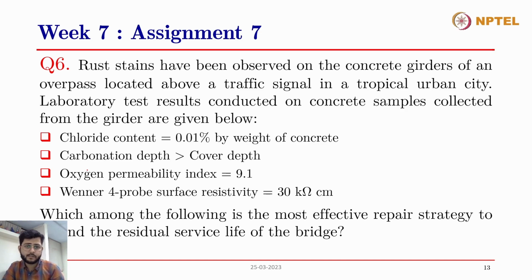The chloride content is 0.01% by weight of the concrete. Carbonation depth is greater than cover depth. Oxygen permeability index is 9.1. The four-probe surface resistivity result gives us 30 kilo ohm centimeter. The resistivity has been found as 30 kilo ohm centimeter, surface resistivity.